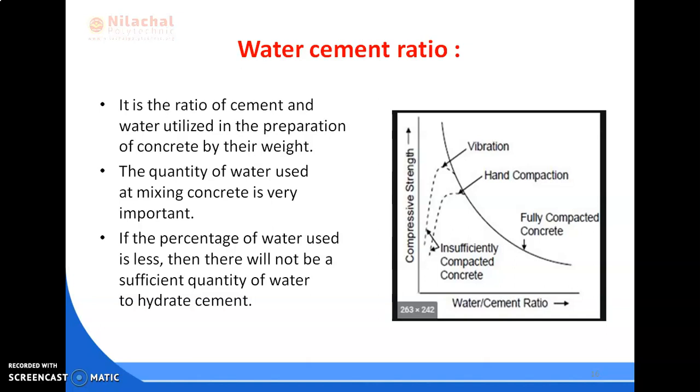Whatever we find out during the mix design process, it is better to use that particular water cement ratio. Otherwise, we can face different issues during the preparation of concrete. So, the water cement ratio plays a vital role in the preparation of concrete, to get strong and durable concrete.